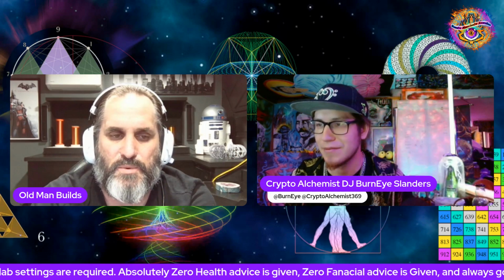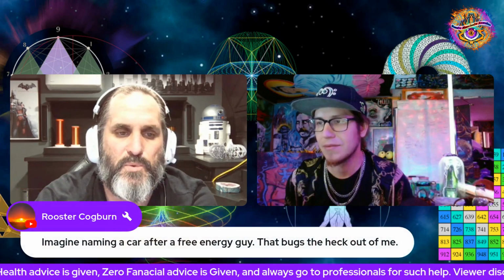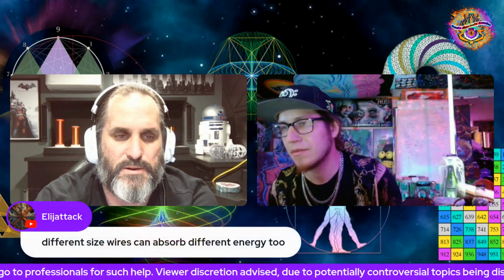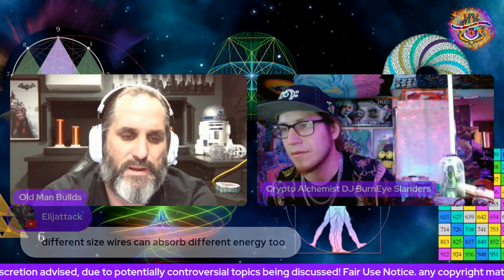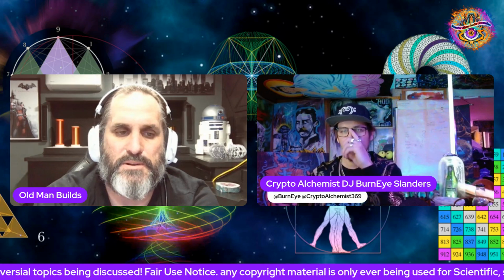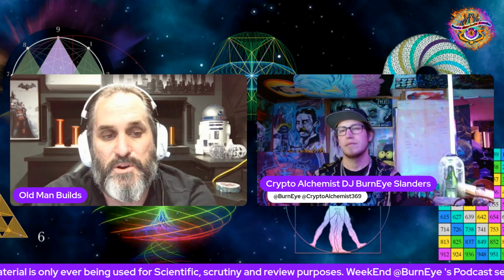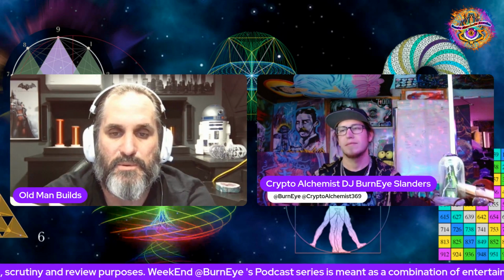Full bridge rectifier twice. When you're in high frequency, make sure you have high frequency diodes. If you want more amperage, put slow moving diodes in there, and it'll create more amps because it'll slow it down. Basically, it's a natural duty cycle when you put in slower ones. So then the amperage will go up and the voltage will go down. But when you put in high frequency diodes, the voltage goes through the roof and it just flows, and you'll be able to fill caps.